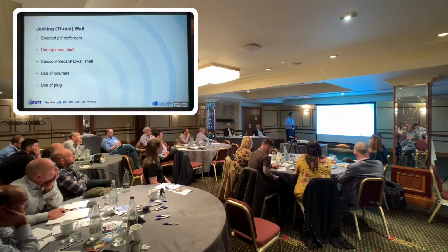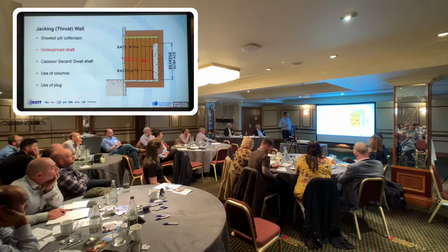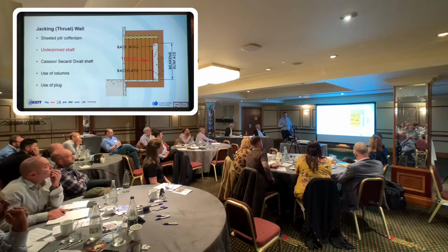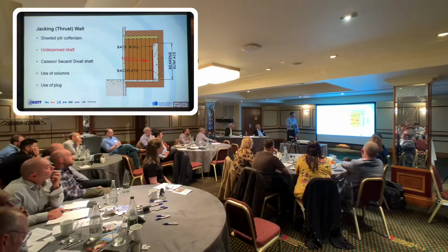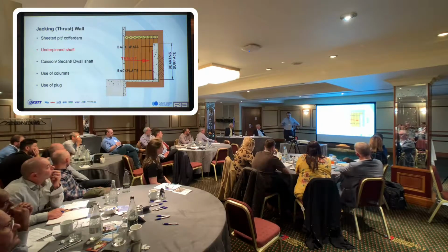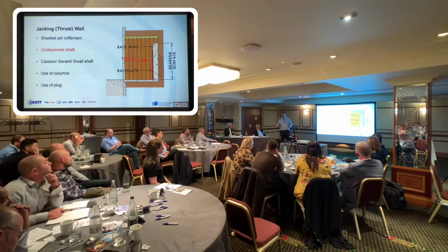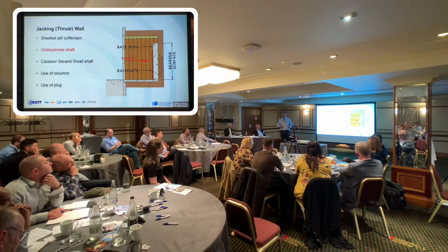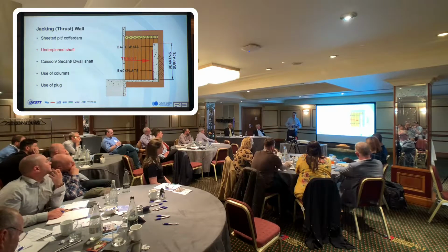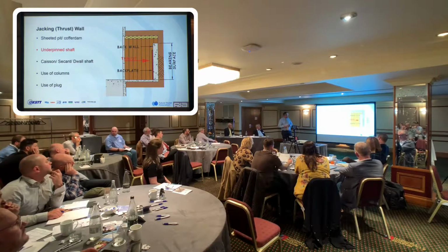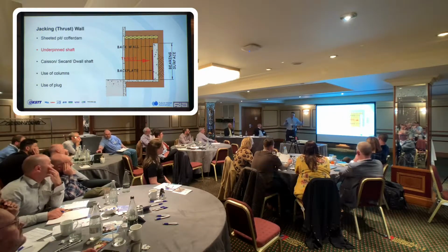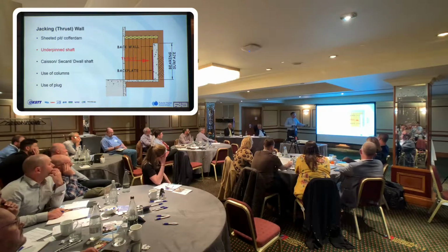I've got an underpin shaft. This is probably the wrong terminology. Well, it is the wrong terminology. It is an underpin, but it's what people would call a back shunt or maybe a front shunt. So if Graham talked about sometimes the site can be constrained, you might have a smaller shaft than you really need to be able to launch the machine from. And I would add, if you need to constrain the diameter of the shaft, it may mean that you physically haven't got enough space to put the machine in and get it out. So in which case,